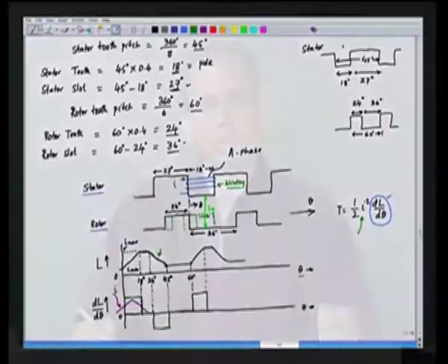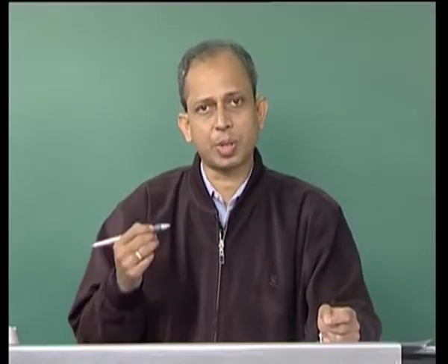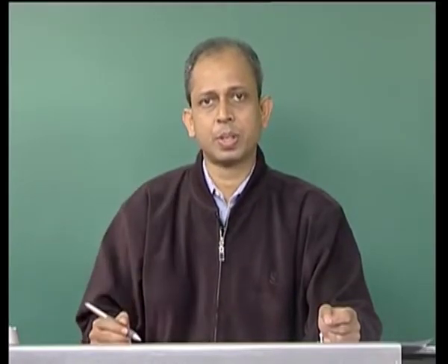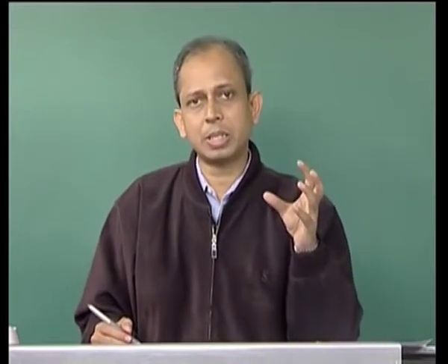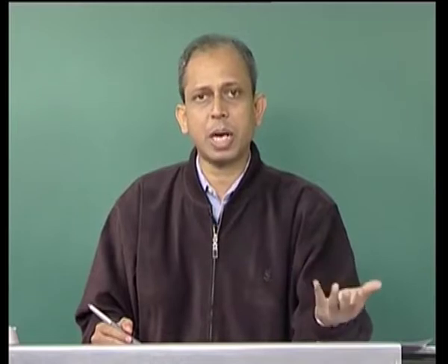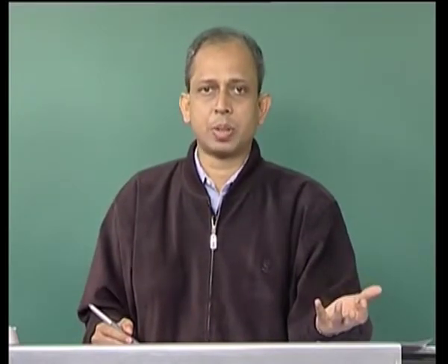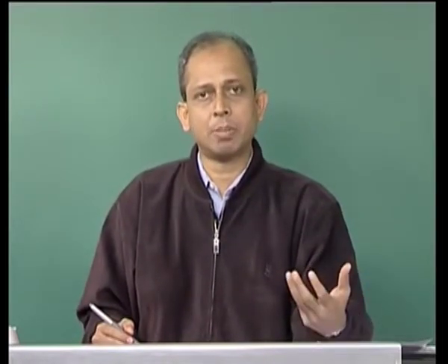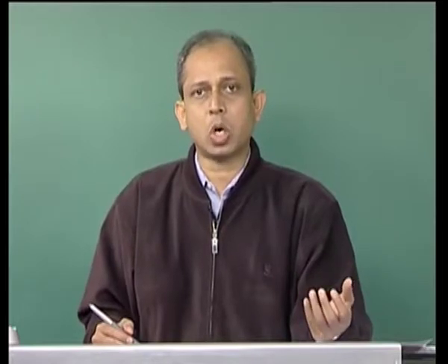The current in the winding has to be optimally switched in such a way that the current only exists during the positive dL by d theta, and if we can ensure that, the torque production is maximized, and we can have a motor with good torque per ampere.